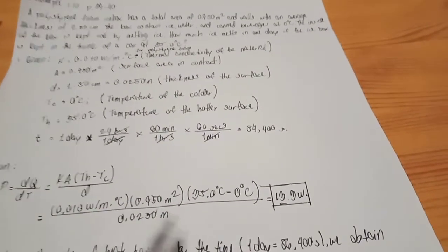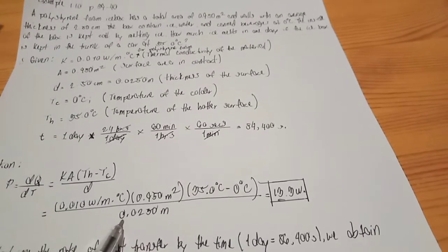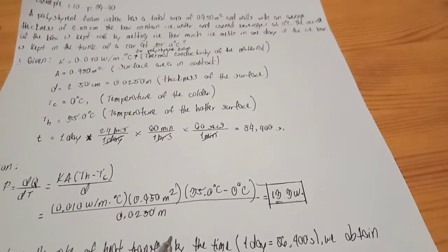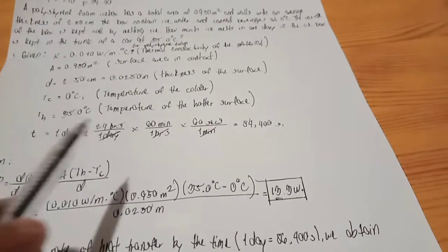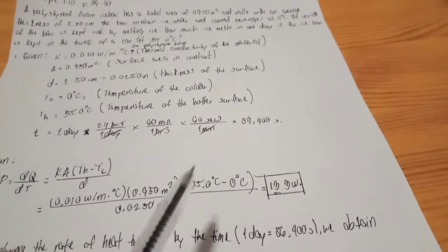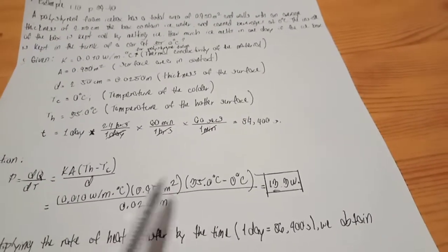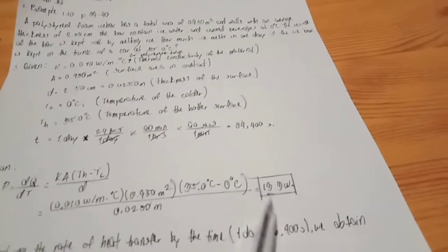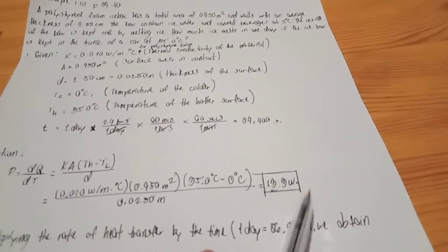Then we divide by 0.0250 meter, the thickness of the surface, and we substitute. So this is the answer, 13.3 watts.